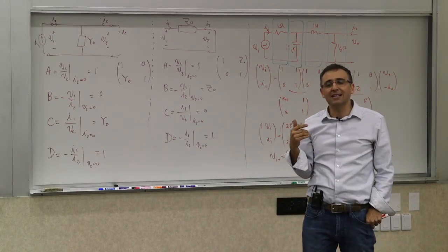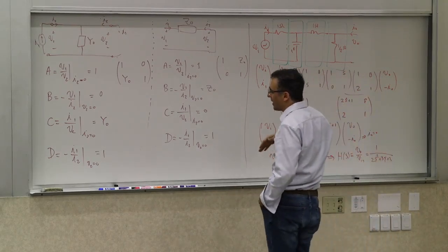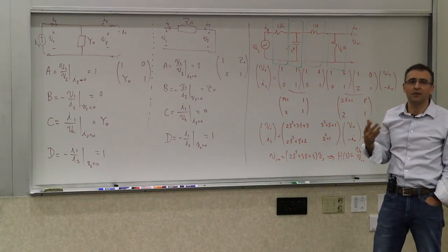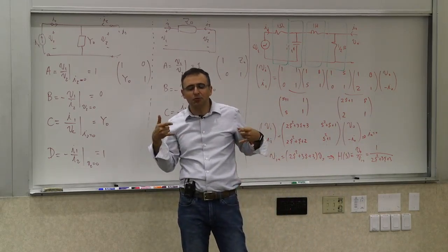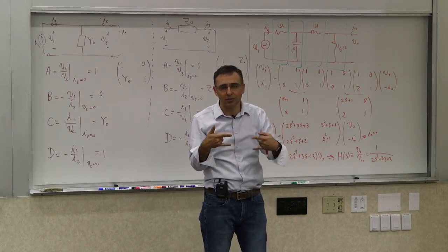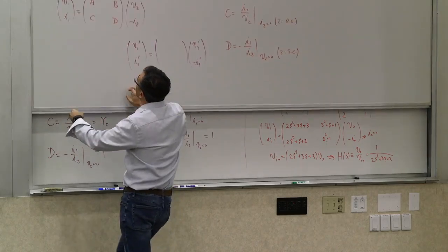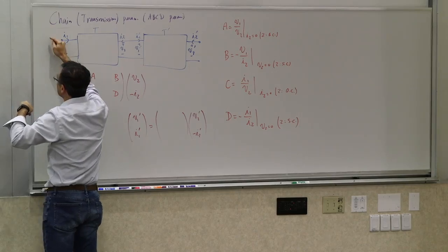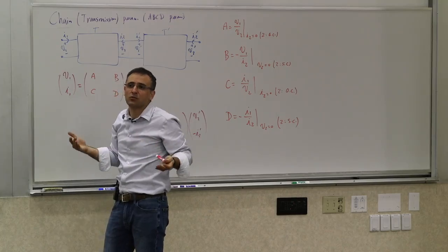In those cases, you actually want to deal with a situation where your source has a fixed, well-defined impedance, and often you want it to be a resistive one. A very common value for that is 50 ohms. That's why a lot of high-frequency measurements are done with 50 ohms. So in S parameters, you look at the ratios of the reflected power from the port to the incident power. If you have a port you're looking at, you have an incident power, and then you look at the reflected power coming out of there. The ratio of that reflected power to the incident power, when properly normalized, is called S11.